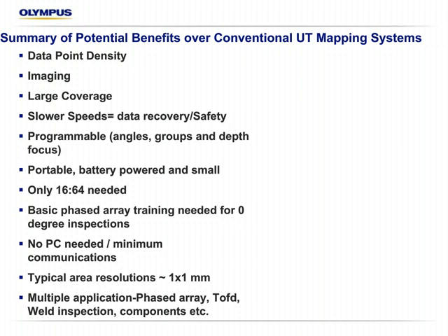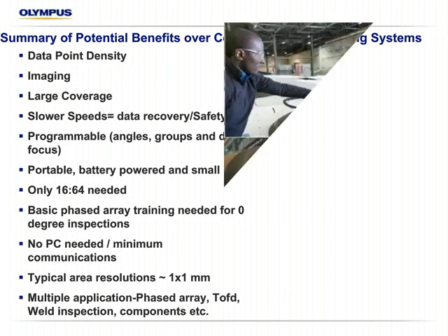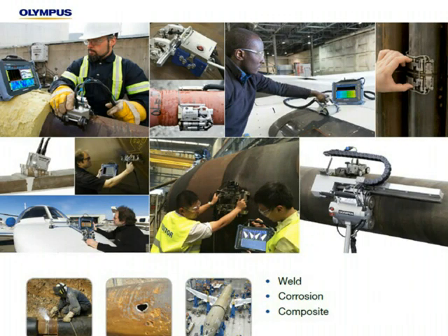And then that's a very flexible unit when you use a phased array unit, because that same unit can basically be used in all kinds of ultrasonic tests, from automatic weld testing to component testing. Usually have the ability to do time of flight diffraction as well. So it's a very beneficial, flexible system.